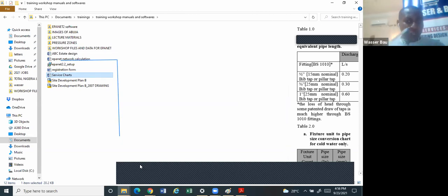Now, I agree with you, because what people do these days is that if the pressure in the network is so low, you can get a pressure boost and attach to that equipment. And again, one other thing you mentioned, which I like, is that it depends on the natural condition. There are some conditions that are favorable to you to have a pressure that is up to 5 or 6. And there are some conditions that are flat land. So if you want to achieve such a big pressure, it means your elevated tank might be beyond your budget. Let me use that word.